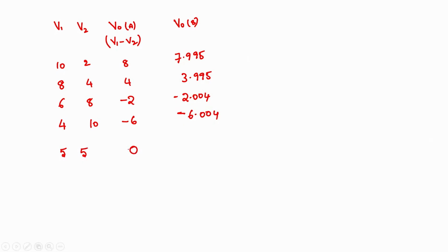And we have also done other experiments when both inputs are same, which are nothing but common mode signals, but actually speaking the output should be 0, but we are not getting 0, we are getting some value of 0.811 milli. And even it is almost same even when I am taking different voltage value of 10 and 10, which is of minus 4.1323 milli.